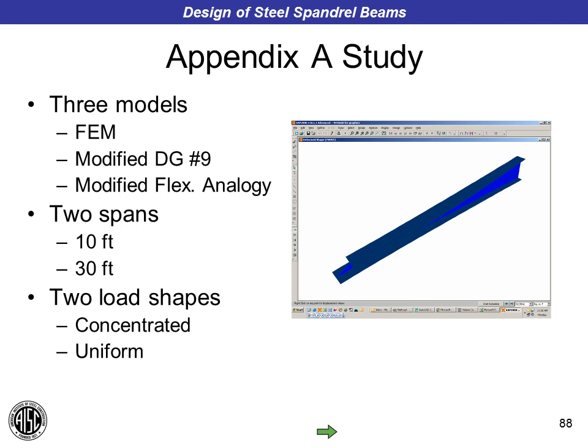In reality, the floor slab will provide some restraint against the twist, but we neglected this in our analysis. We assumed that we had a true pin at the top flange of the beam, and the top flange of the beam was only laterally restrained.